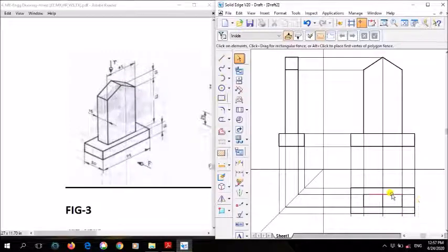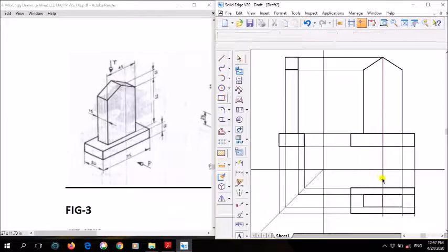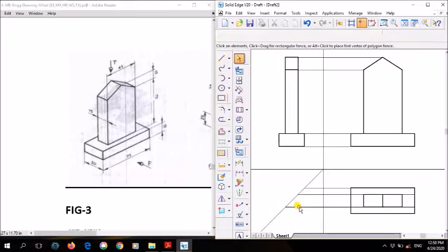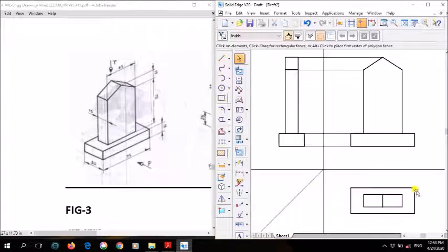Clear? So next, you delete this extension line, or you rub it out later. Whatever extension lines are there, you just rub them. Why? Because when you do the dimensions, these extension lines collide with the dimension lines, and there should not be confusion in the drawing. For that reason you rub these extension lines later. That's why the extension lines should be drawn using thin lines, so that they can easily be rubbed.